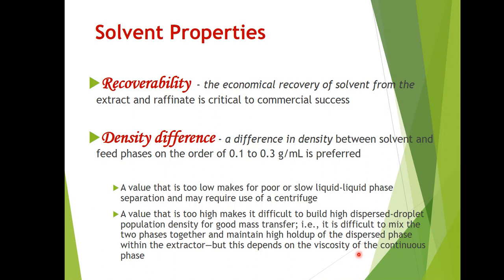So we have to be very careful when we read the problem as to what it dictates us to consider as the dispersed phase or the continuous phase, because it really matters as to how big your extraction unit is if your feed is considered the continuous phase or the dispersed phase.